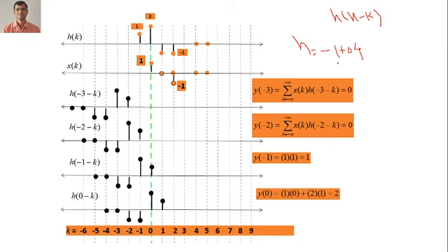So as your signal is going to start from minus 1, directly we will start from h of n, and you will put the value of n as minus 1, so h of minus 1 minus k. First, what do you need to sketch? We need to sketch h of minus k, then put minus 1 minus k equals 0. So the value of k is equal to minus 1. So we will be getting the signal like this.